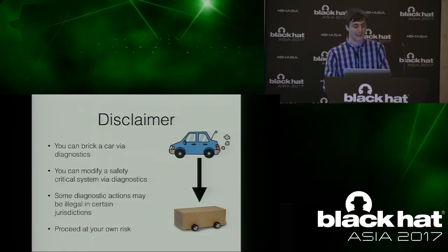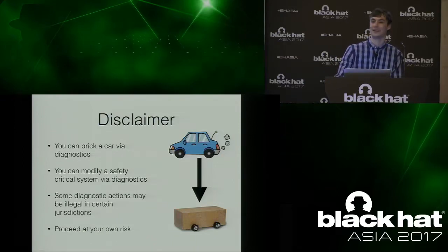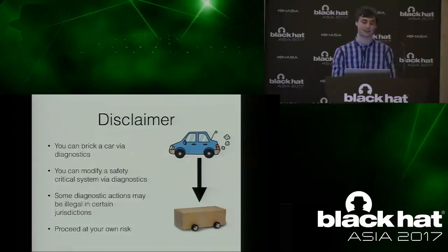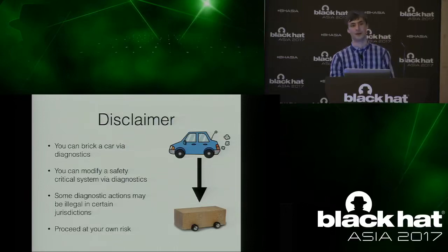But let's start with a disclaimer. You can brick, i.e. render useless a car via diagnostics. It is doable. You can erase firmware. It would not work out well. Your engine will not start if it has no code. You can also modify these systems via diagnostics, and they are safety critical systems, so you need to be cognizant of that. And some diagnostic actions, things like maybe changing VIN numbers or odometer values, might be illegal where you live, and that would be bad for you to do those. So this is a very proceed at your own risk, know what you're getting into. This stuff can be dangerous.